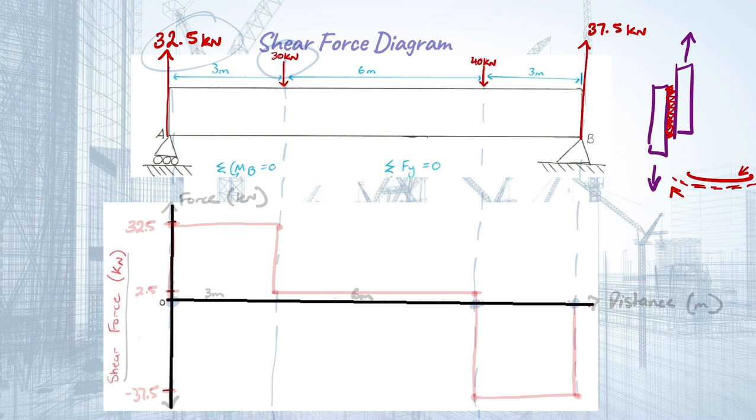So we want to work out what the magnitude of the shear force is going to be at different points along the beam. This will help us to work out where the forces essentially are greatest, and that'll help us in our calculation of ultimate bending stress. So the way we do this is quite simply, we take our shear force diagram. So it's just a simply loaded graph.